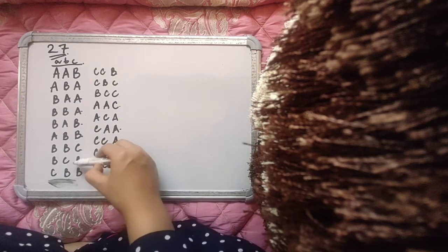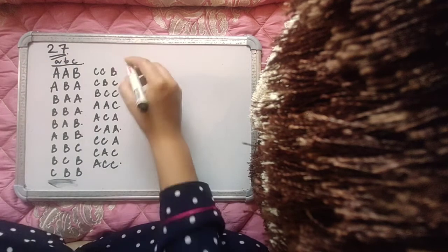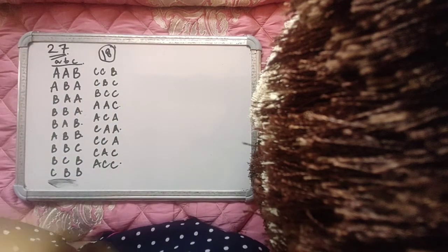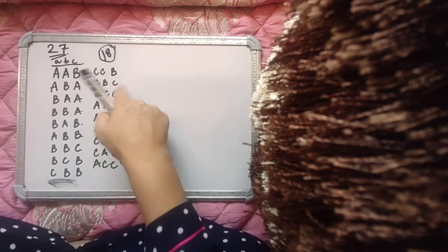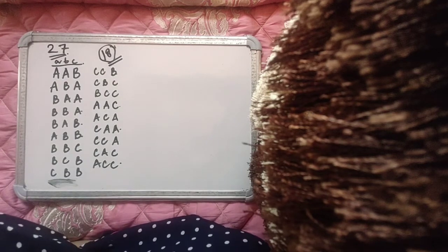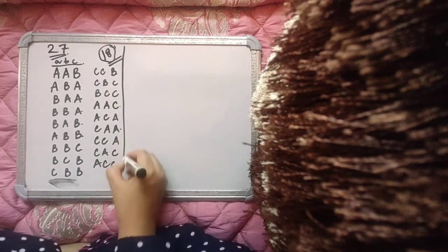1, 2, 3, 4, 5, 6, 7, 8, 9. A total of 18 switching states, right? Where two same input phases and one different input phase are sampled at the output. So these are the main 18 states. Now we are left with 27 minus 18, that is 9 switching states. These are the main 18, or active vectors you can call them.